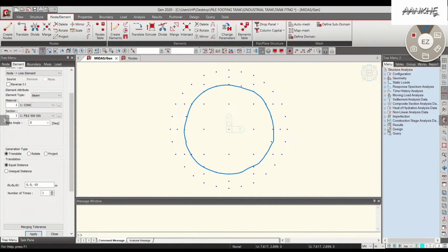Right? But what we have done, because it is a less important structure, we have assumed that the tank will be a 1D element with all the mass concentrated at the CG. Obviously it will be the CG. So what we have to do is translate this particular node to the tank height. So we need to translate it now. Let us remove it from screen.